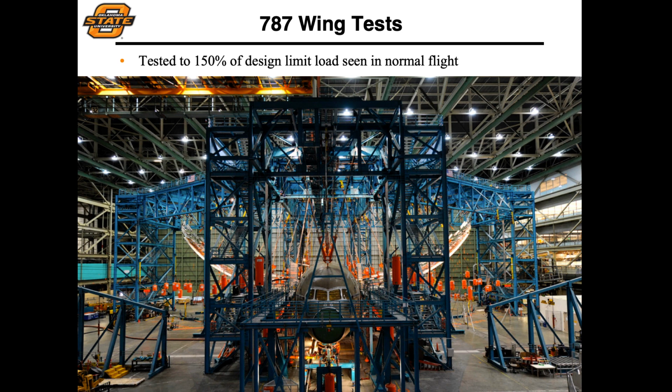So that's the point where you want to make sure your aircraft is not going to fail. If it gets to 151% and fails, that's fine. You're perfect. But you've got to make sure that it doesn't fail at 149%. So you can see the extreme flex that these wings are undergoing. And trust me, if you looked out the window and saw the wings undergoing this type of deformation, you'd never notice because you'd be screaming along with the rest of the passengers based upon whatever the aircraft was doing to put the wings in that extreme loading scenario.